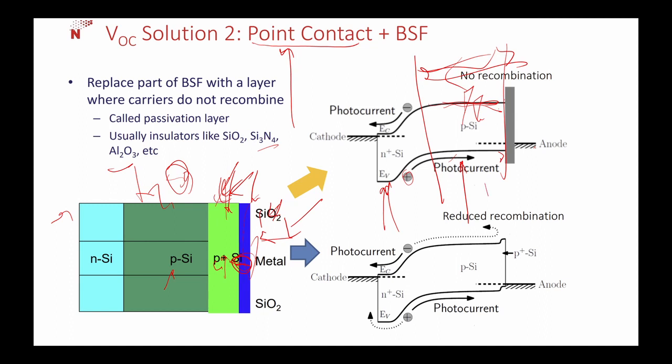If you increase the doping, the back scattering changes, or this hill will be lesser, and other effects will also come. If you increase the doping of this region, it will reduce W, which is the depletion region width. So ultimately you are losing efficiency again if you increase the doping.